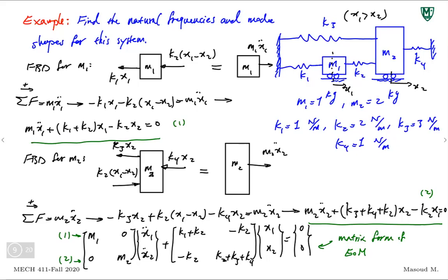All right, how do you check? Are both of the matrices symmetric? Yes. Mass matrix is symmetric. Off diagonal elements are 0. Stiffness matrix is symmetric. Off diagonal elements are the same. They're both minus K2. It's the best check possible. If you get to this point and your matrices are not symmetric, go back to the equations of motion. You made the wrong assumption somewhere or made a mistake moving things around. Right? Double check.